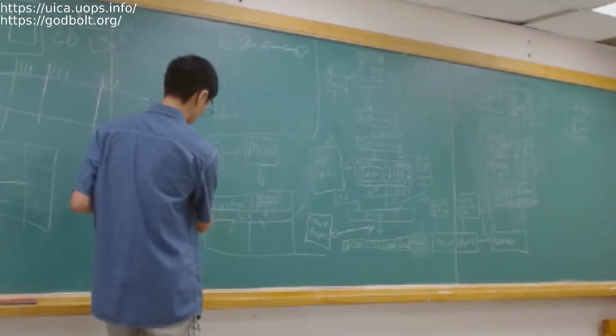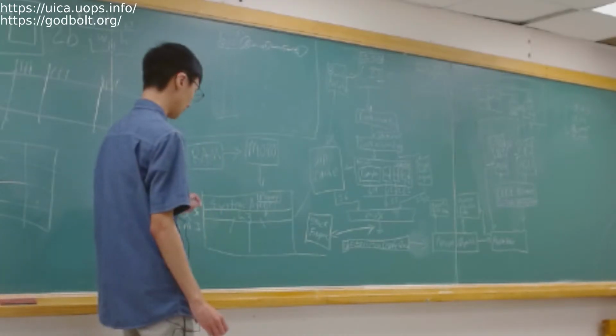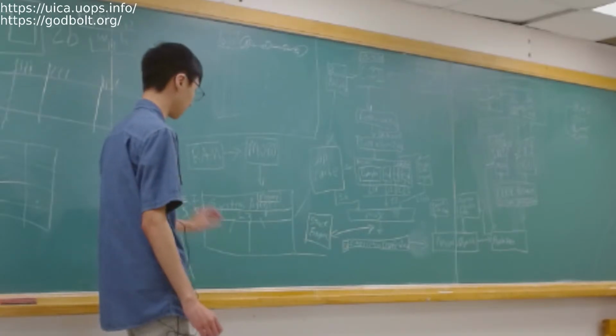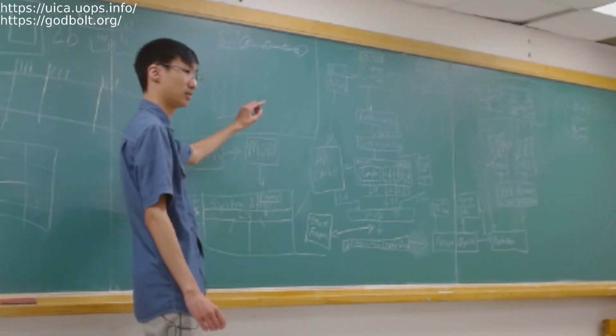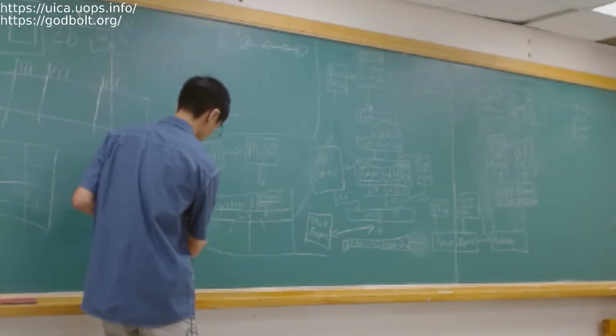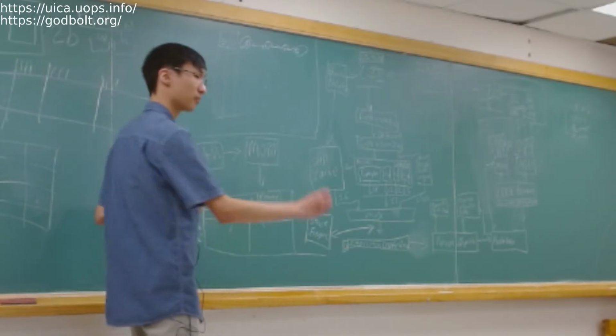And so at the very start, this one was probably invalid. And then what happens is if this one goes to grab it again, and this one hasn't flushed it to the L3, then this one will become owned, and this one will become shared, okay?